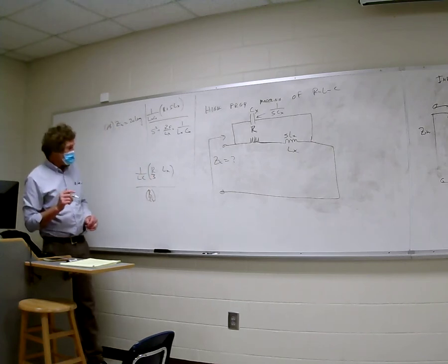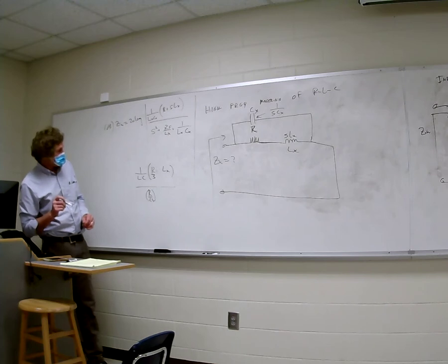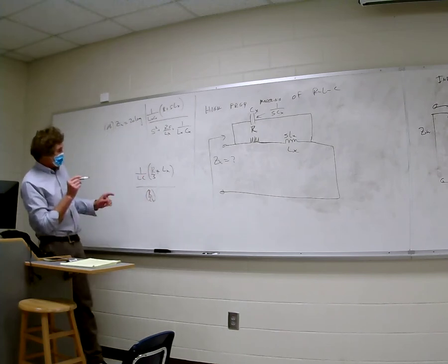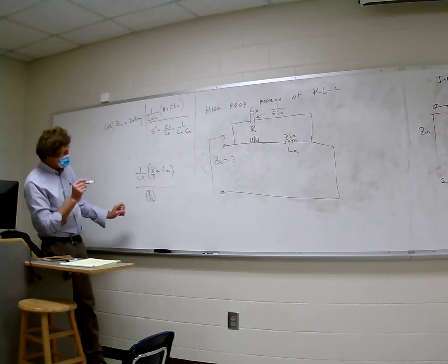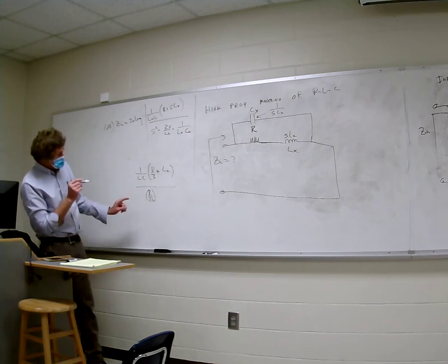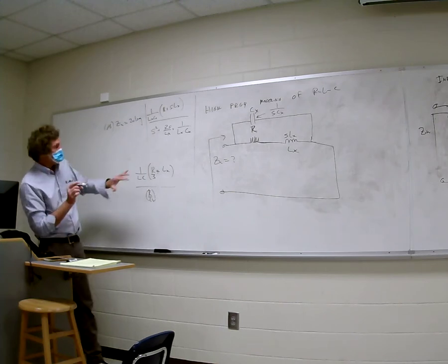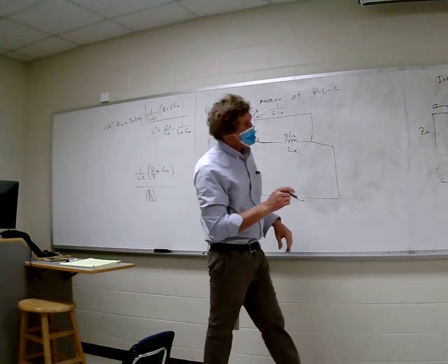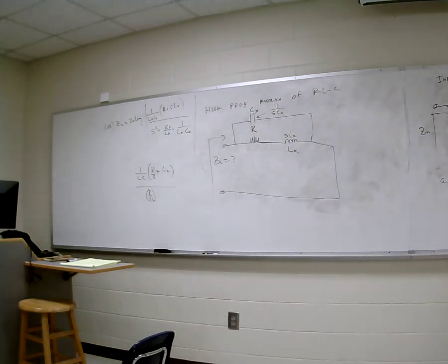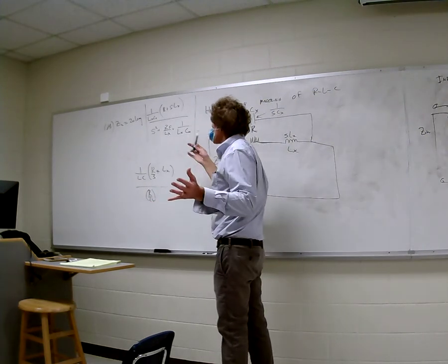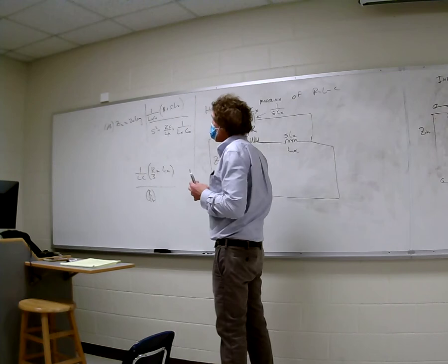All right? Now, if you take a look at that, I'm not going to mess with this much longer. If you look at this, you get a 1 over C, and I can keep playing with this. Anyway, you can evaluate that depending on the component values. That's the value you would use to calculate this peak. You take 20 times the log of this thing at resonant frequency, which will cancel that and that. You can do the whole thing, and that will be the peak value.